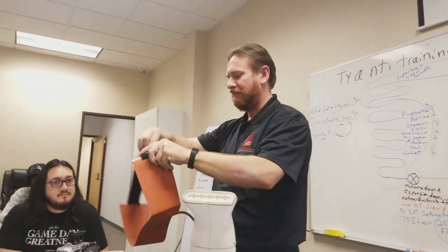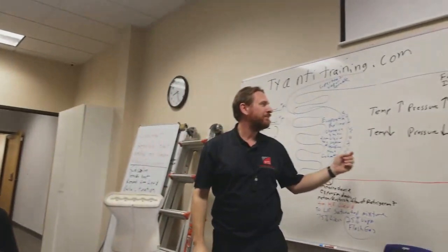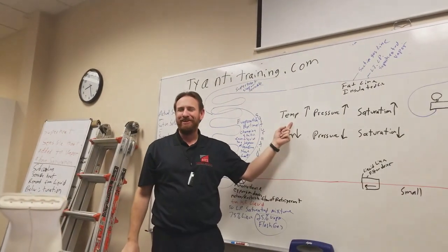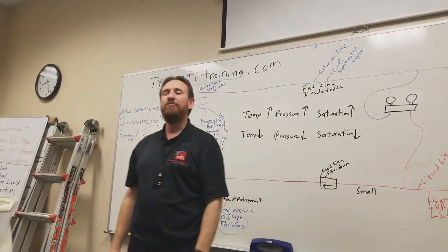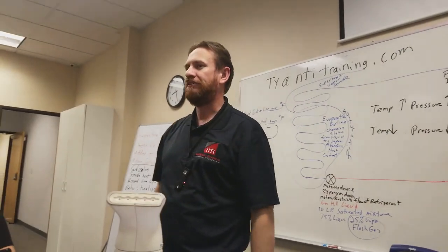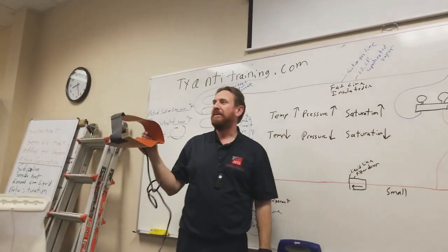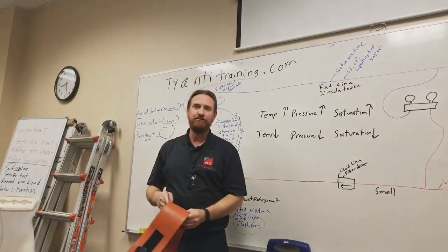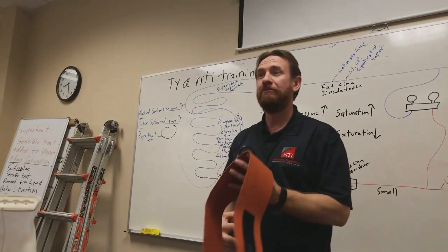Wrap it around, Velcro on it, plug it in, it heats the tank up. Now if I heat the tank up, what's going to happen to the temperature of the tank? What's going to happen to the pressure? Saturation temperature? When we charge refrigerant in the unit sometimes in the winter, or when the temperature outside is lower, we have to use these tank heaters to heat that refrigerant up so the pressure goes up so we can get the refrigerant to flow into the unit. It's the thing that we'll sometimes have to do.